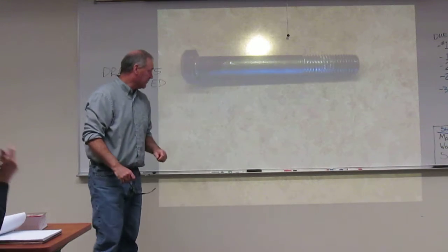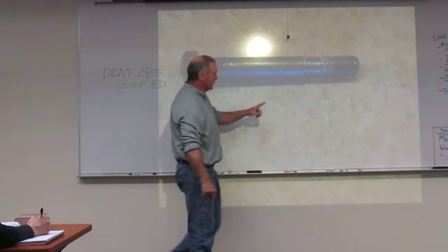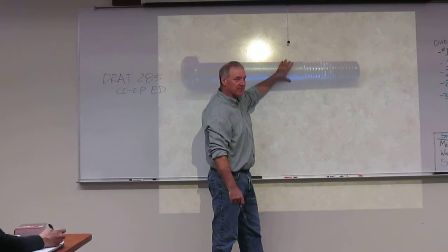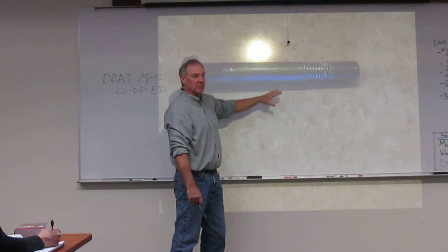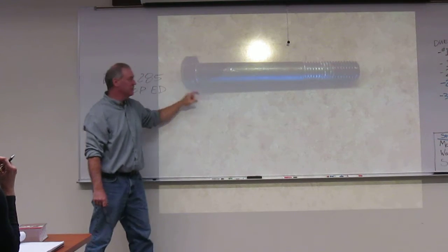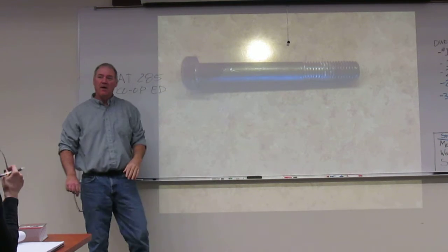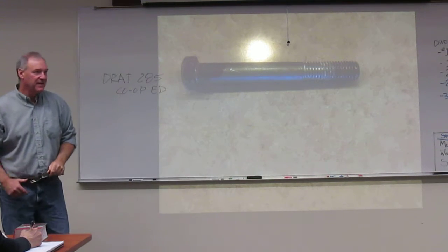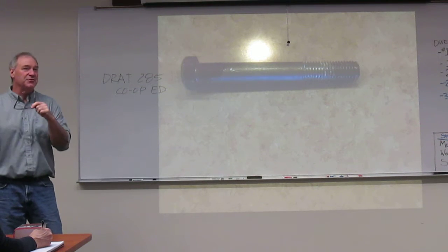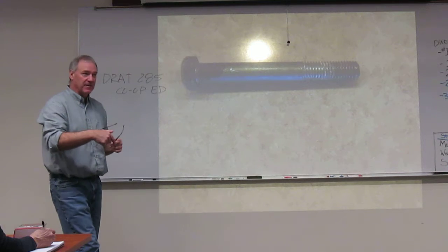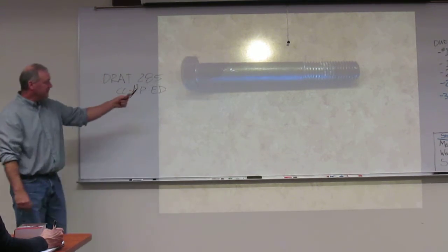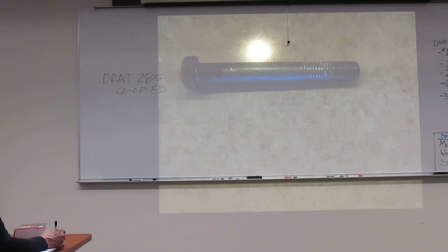They have been set up to where we can use them in multiple devices. When we're dealing with a cap screw like this one, the distance these threads come from here to here is proportional to the diameter of it. This open shank right here is proportional to the open diameter. This hex head on the top is proportional to the diameter. It's all done off of proportions. So therefore, we can just give a recommendation or an approximate shape and then give them the thread note, and they will be able to get the right device. So this is an example of a cap screw and what's going on.